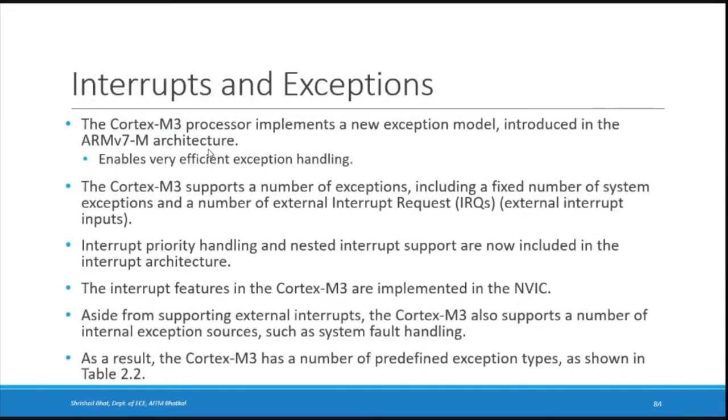So next we have interrupts and exceptions. This interrupt controller deals with the interrupts and exceptions. So what are these interrupts and exceptions? Whenever the processor needs attention, some signals will be sent by some particular processors or maybe some hardware to the processor to indicate that it has to stop its current execution, and there is some critical thing that has to be serviced first.